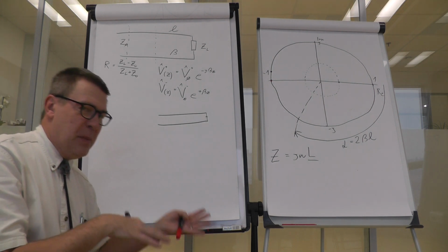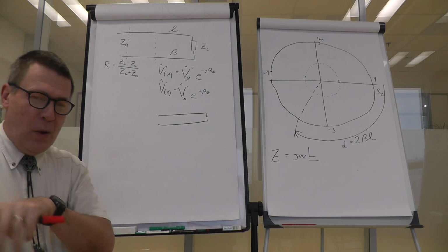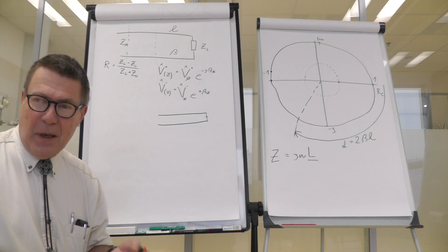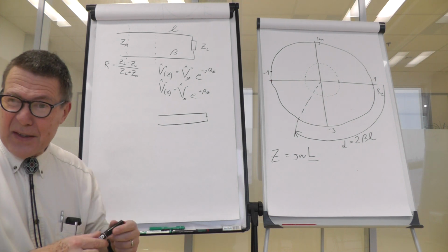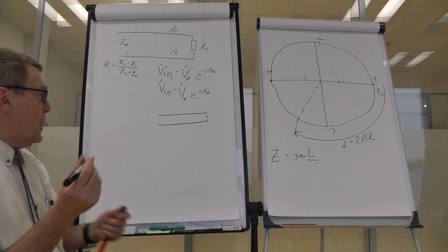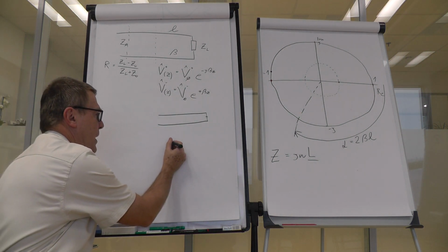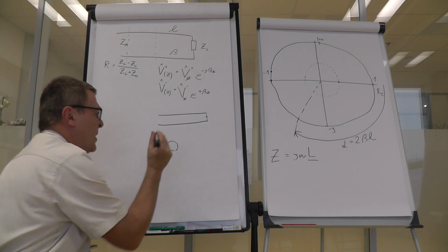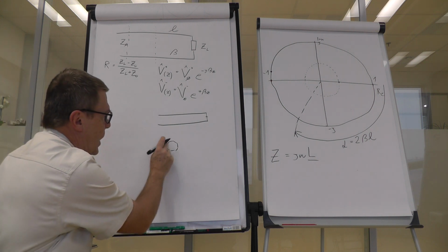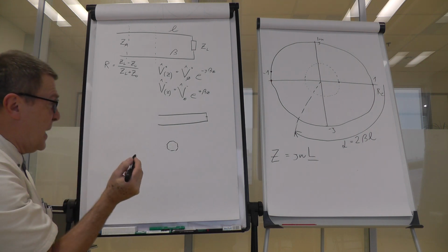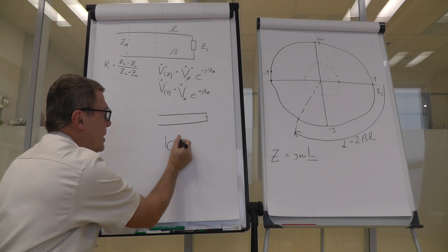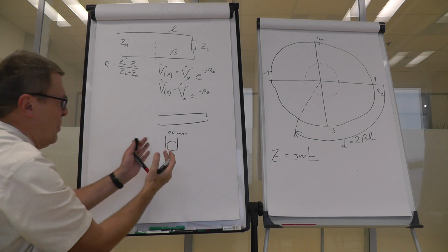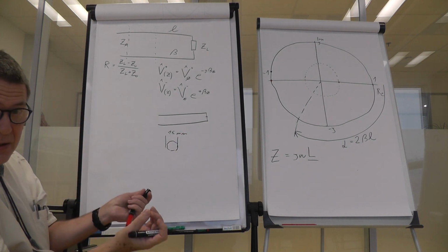let's say at frequencies between 1 and 25 gigahertz, you use packaged semiconductor devices quite often, like transistors. Such a transistor, for example, there is a PM from HP or Agilent today. It's something like a small ceramic hexagon. This is 1.8 millimeter. And this small hexagon has the chip inside, and then it has got some leads.